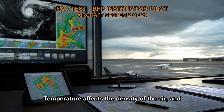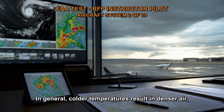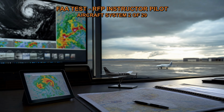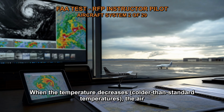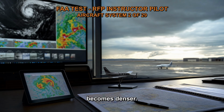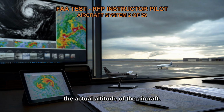Temperature affects the density of the air, and changes in air density can impact the altimeter's readings. In general, colder temperatures result in denser air, while warmer temperatures result in less dense air. When the temperature decreases, colder than standard temperatures, the air becomes denser. As a result, for a given pressure level, the altimeter will indicate a higher altitude than the actual altitude of